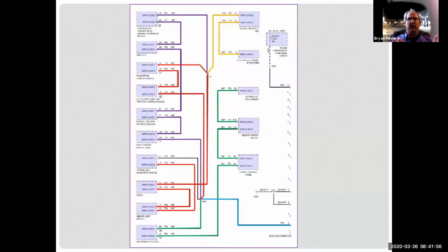I kind of drew some different lines through here to show the different ways these are connected and the different ways they share information. And this is just respective of where I need to do if I had a problem with this car, which is what I already did do. And we've actually taken one of these cars and I shorted the entire network and the dash looks like a Christmas tree. All the lights are lit up. Steering doesn't work right. Nothing works right. Car still drives and shifts fine because the engine and transmission have their own network. I couldn't talk to the engine or transmission, but they work just fine. So this is using a diagram here to look at my topography and kind of figure out how that is.